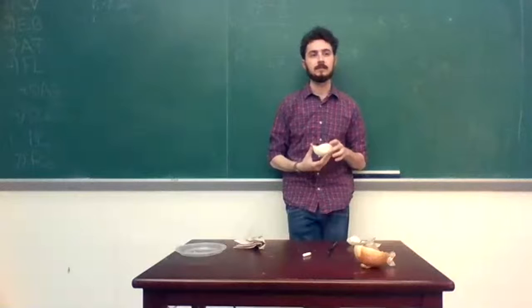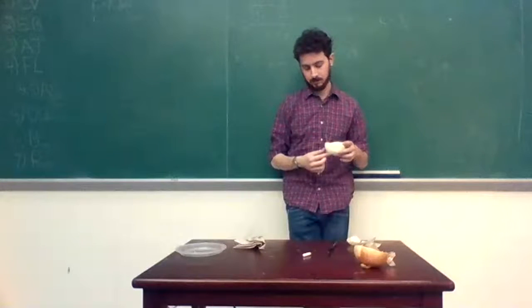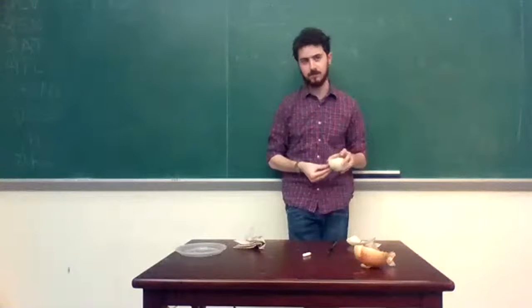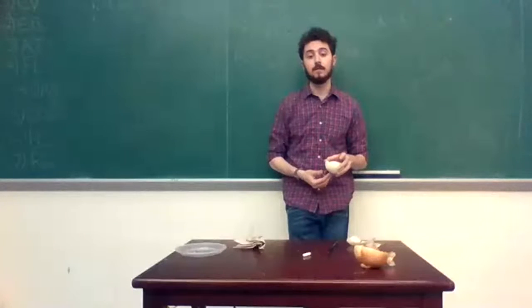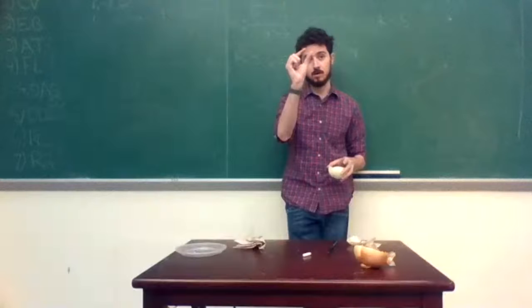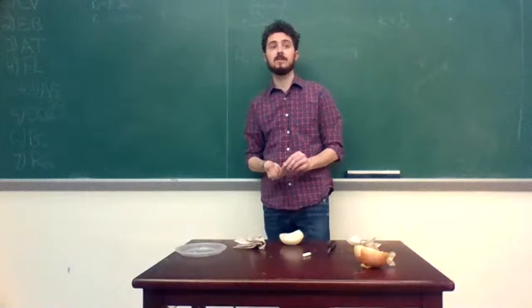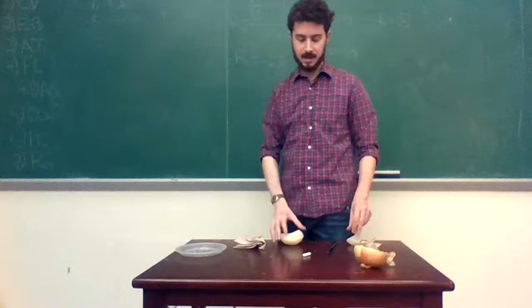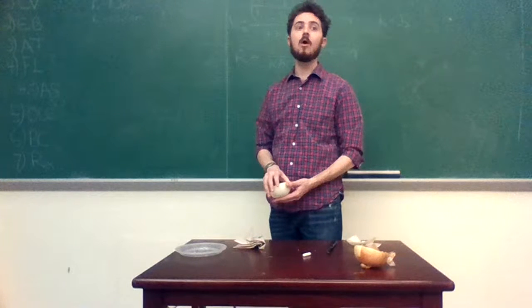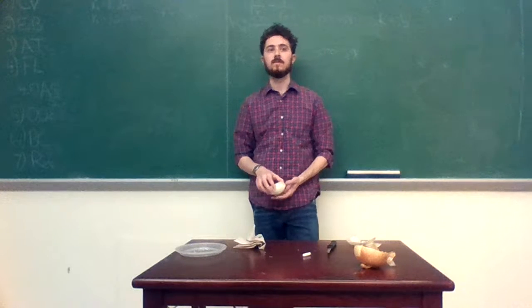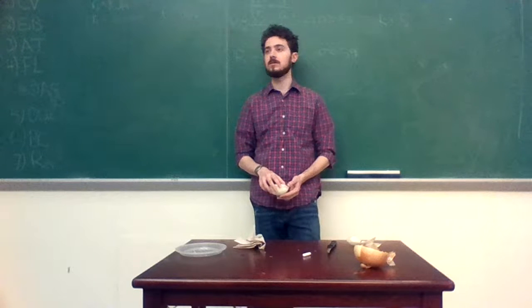Yes? So when can we make that judgment call? Well, if you're solving a cylinder problem with a relatively thin piece of insulation, you could do a little back of the envelope and say, I just treated this as L over kA, am I close? And more often than not, it's going to be pretty close, if R0 and R1 aren't super different.